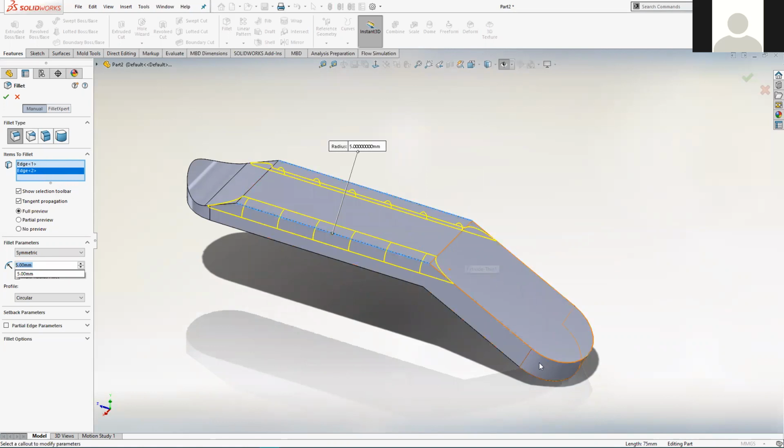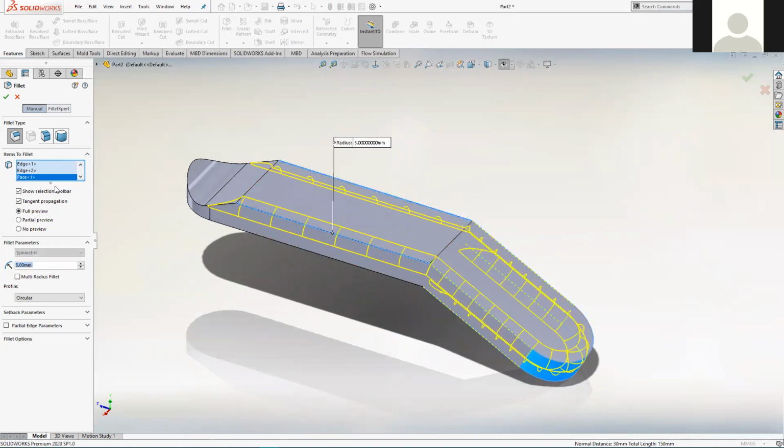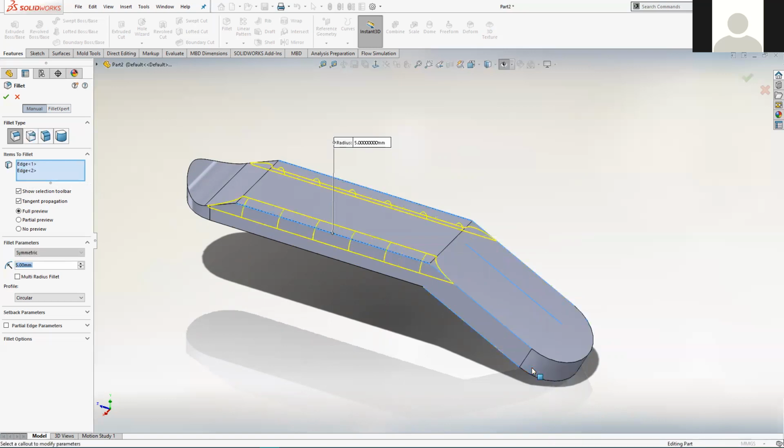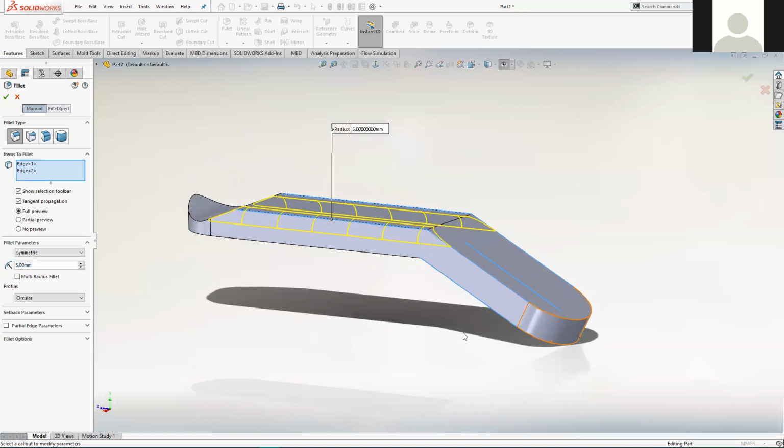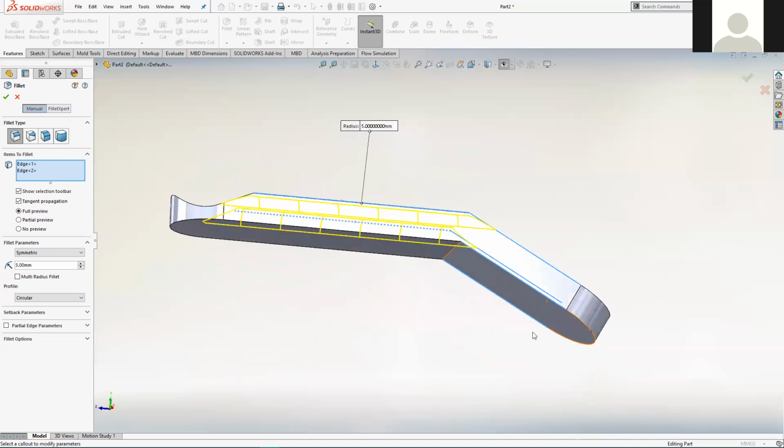If you click something in error, you can get rid of it by, you can actually click on the item again. So you can see that I'm selecting that bottom face, and then by clicking it a second time, it's becoming unselected. That can be a little bit sketchy, in that at some points you try to click to deselect a face or an edge and it actually clicks on a second face, so you've got double the problem then.